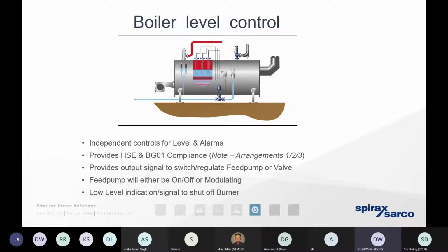And that works by constantly drip feeding in a very, very small mass of high temperature water into the boiler. So the boiler can ensure that the steam is being produced in equilibrium with the requirements, and it means we don't get that quenching effect. It means that we've got steam that is more readily available. We get a better condition of steam being produced for the process. And it also means we're working more efficiently from an energy perspective.